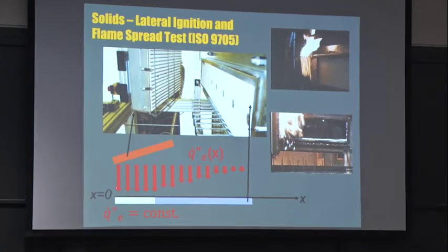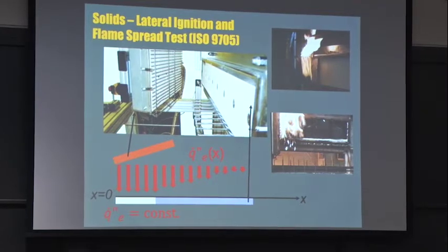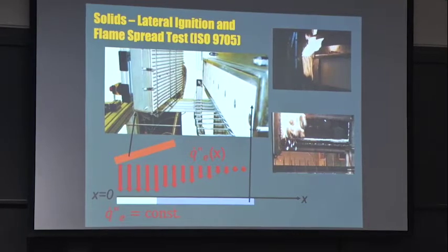In this area here, you're going to have the highest heat flux, but then it decays in such a way that at each point you get a lower heat flux being imposed. I'll explain the nuances of the test in a minute, but effectively you heat this up, at some point you ignite the flame, and then you measure how fast it spreads. Needless to say, this test was originally developed in the 1950s, and then it was taken by Quintiere, who developed all the theory behind it and extracted the material properties. But it has no diagnostics. You see these little sticks here?